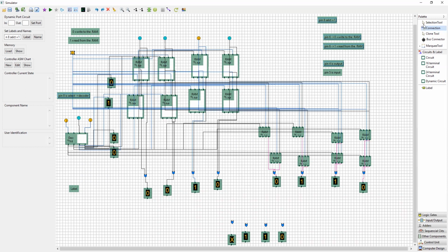That means obviously then I need to deal with the decoder. Decoder 10 or 11, only two options. So I will select the third row now. For the third row I will select 10 now. Okay, 110 I want to insert. So to insert into the RAM I have to keep 0 and I will run. 10 means the third row will get selected, right? Yeah, it is 10. You can see this one got high and this third row, everything got selected.